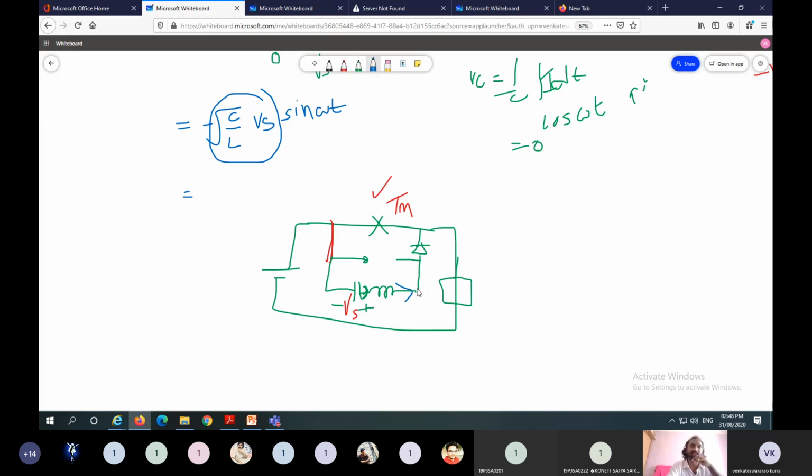And capacitor does not discharge suddenly. It discharges gradually. So the current also increases gradually like this. And this one is the main thyristor. So here, this is the direction of current. So if you assume the main thyristor constant current is 5 amperes, as capacitor discharges gradually, the capacitor current also increases from 0 to 1, 1 to 2, 2 to 3, 3 to 4, 4 to 5.